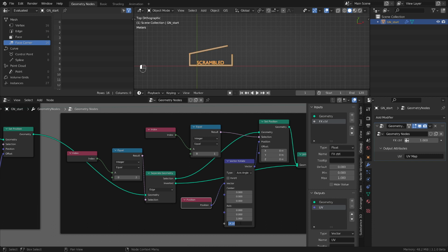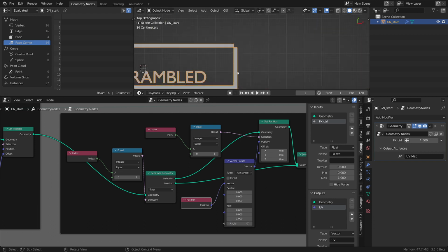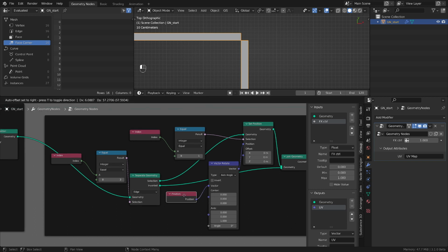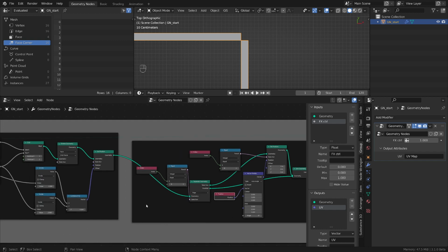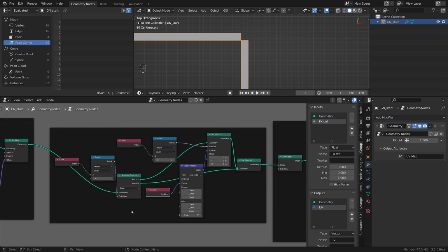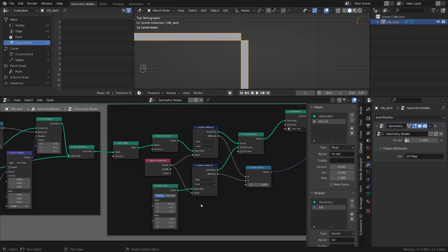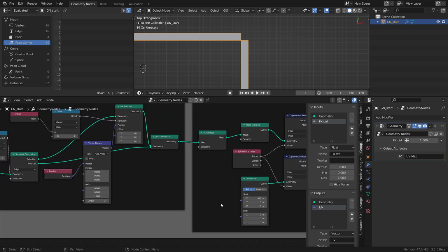But we have a problem now that I want to fix. This is not closing nicely shut. So how can we fix that? How can we fix the lid length? Well, in order to do that, we kind of have to have access to this information from here, this curve line thickness.